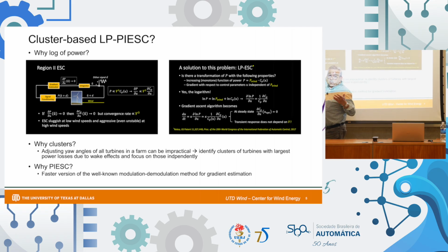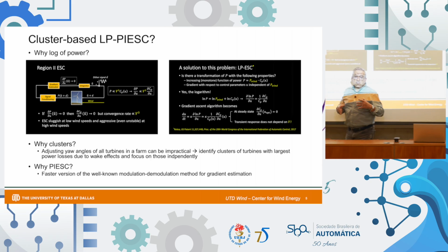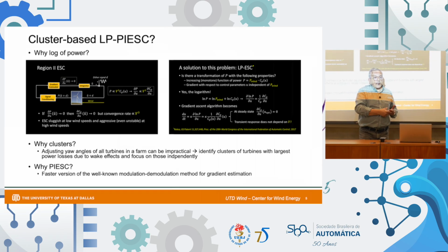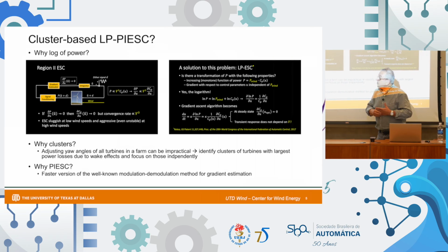And if you want to be non-typical and accelerate the bandwidth of the closed loop system, you will start putting some lead compensation, like the proportional. And then you need to add a dither signal in order to have the persistence of excitation that is required to extract the gradient information.